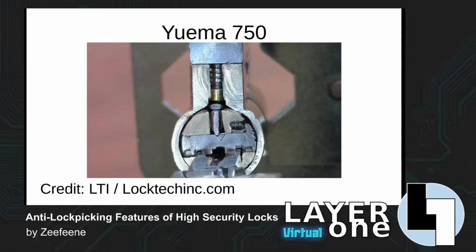The way it achieves that is it has a front portion to the plug, and it has a back portion to the plug. And only when both parts of the reverse sidebar mechanism are allowed to drop inwards by having the sliders correctly aligned, can the front part be locked to the back part and therefore open the lock.